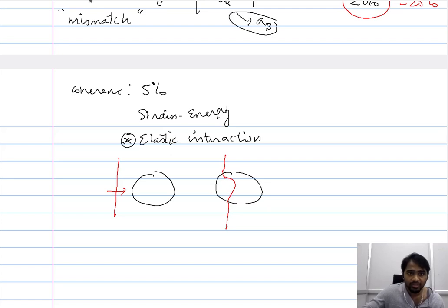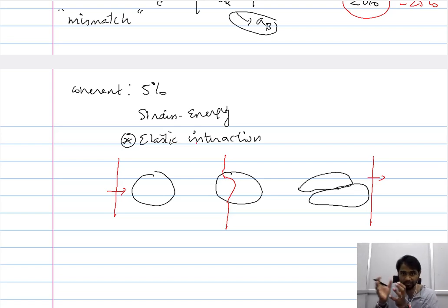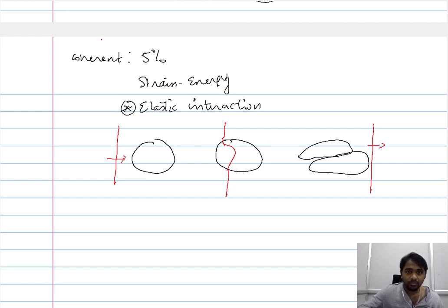It is important to note that since this particle is brittle when compared to the matrix, as the dislocation propagates, this particle breaks, and therefore instead of one particle, you would have two particles, brought about by the propagating dislocation. So as the dislocation reaches the interface, you have elastic interaction. This impedes the rate at which the dislocation is propagating. In addition to that, the dislocation also interacts with the overall particle, and it breaks the particle.